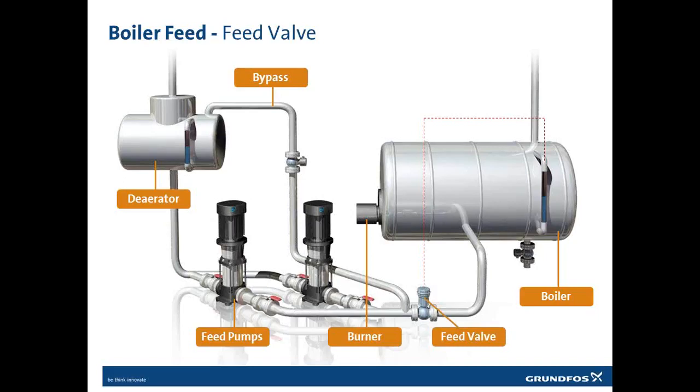In the better built system, or the better design system, they put in a control valve in the bypass system, making sure that we are not pumping water through the bypass system when the feed valve is open, maybe 10% or something like that.